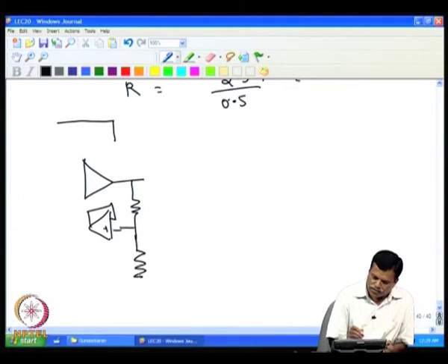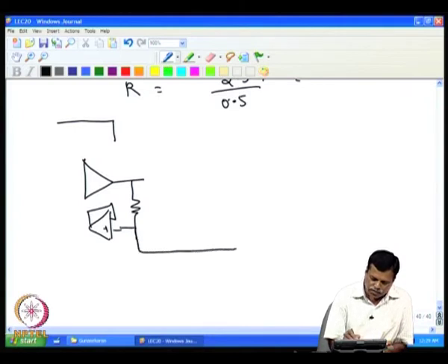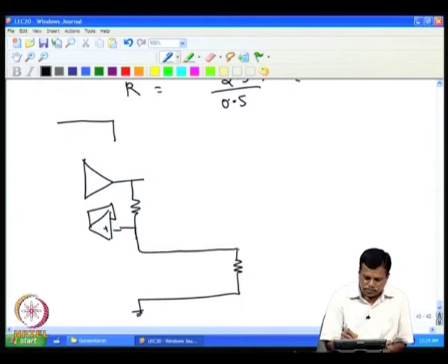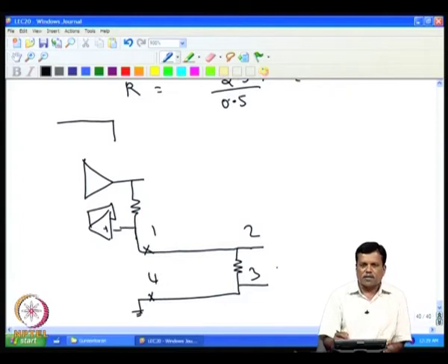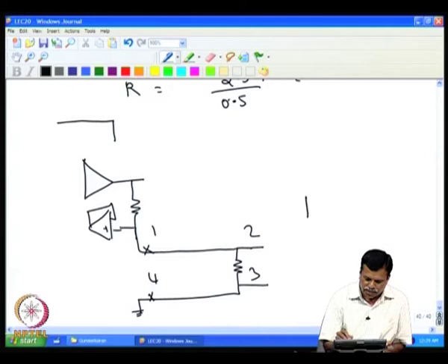So, here, if we draw this, the PRT, normally there is a very long wire going in, and that is the resistance coming back, and then we have to take up the voltage between these 2 points only for measurement. That is why 4 points, 1, 2, 3, 4, and this voltage should be converted to a differential voltage. So, normally to convert we will use a difference amplifier.